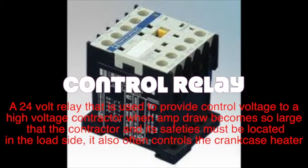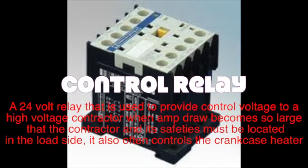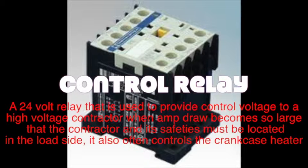Contactor. Control relay: a 24-volt relay that is used to provide control voltage to a high-voltage contactor when the amp draw becomes so large that the contactor and its safeties must be located in the load inside. It also often controls the crankcase heater circuit. That's a control relay.